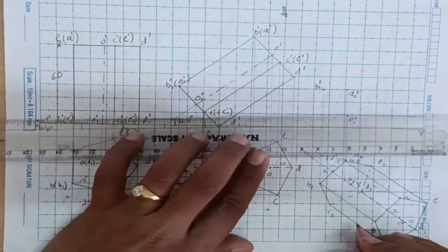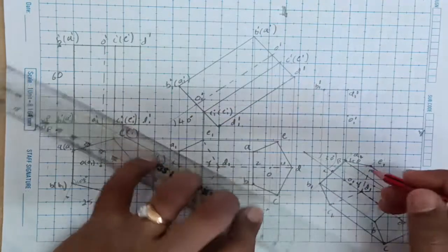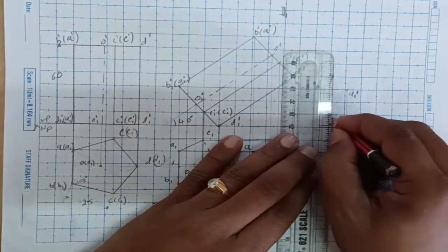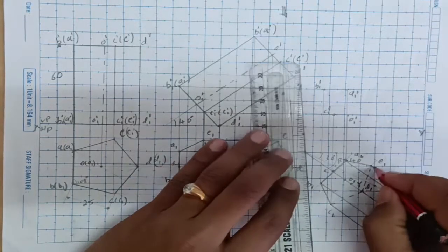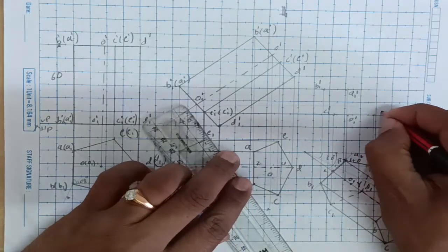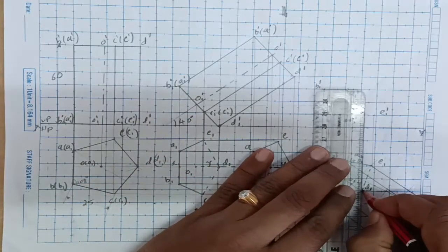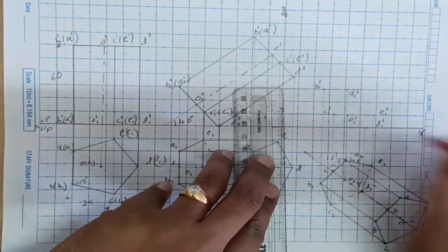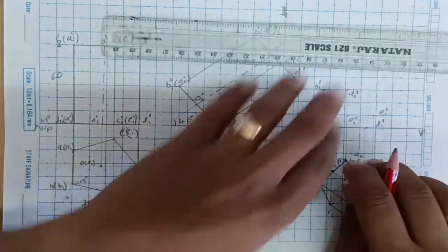And next is C1 dash and E1 dash. Draw the horizontal projection, you join it, then C1 is here, draw the line up to that, and this point I will get C1 dash, and then E1 dash is here, and this point is E1 dash. And now D1 dash on the XY line itself, so you can join up to the XY line and then get the D1 dash. Okay, the bottom we got all the points, and now the same top here, A dash and B